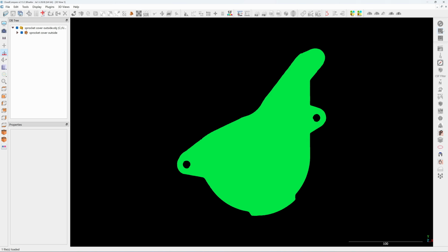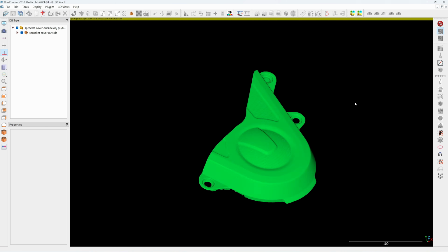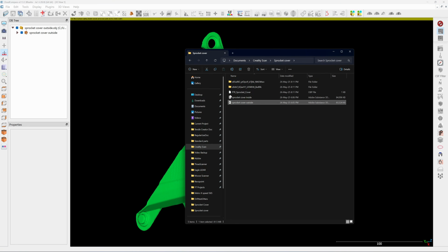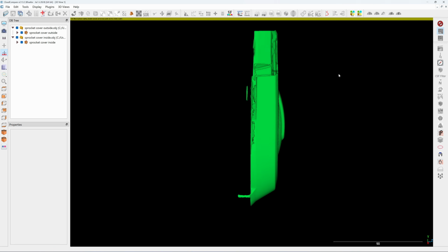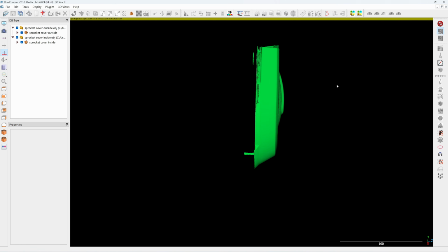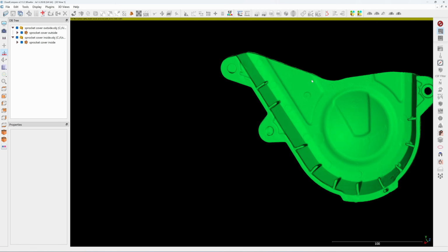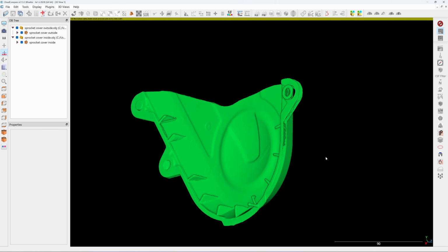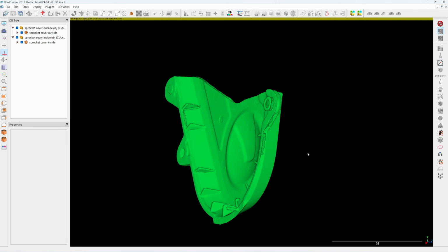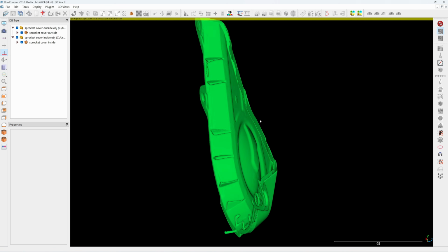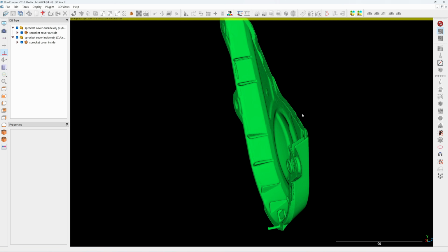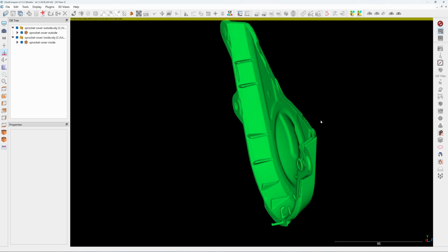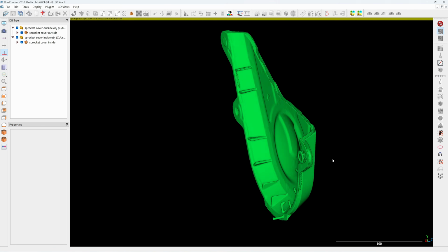Okay, here's the first mesh that he made, and this one will be the inside. The inside and outside have already been aligned, but from what I can see, he didn't align it properly. A little bit of plane shifting. For scanning a thin shell like this, you need complete data. All the side walls, even the small thickness of the wall here, have to be scanned so that you can get more overlap area for merging.